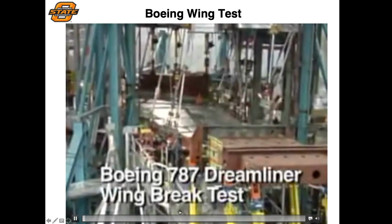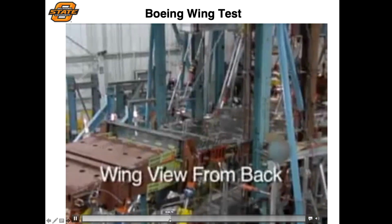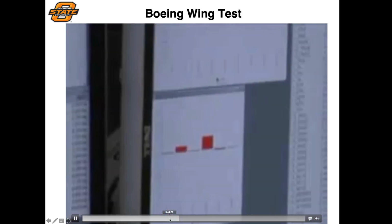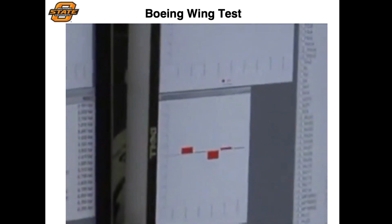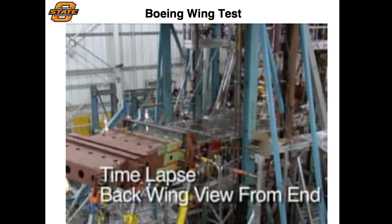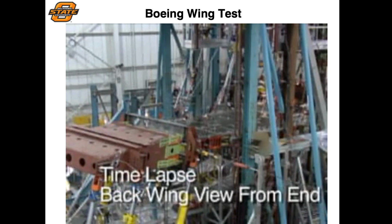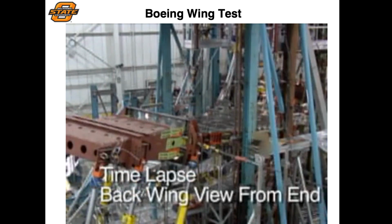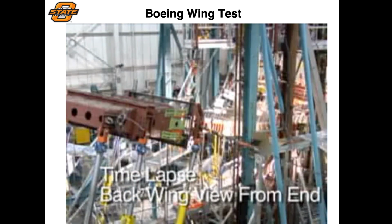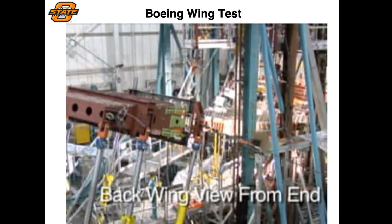So I'm not going to show this entire video here, but you can get an idea of the 787 wing break test as it's going through this process. Again, the jig that is built around this is used to push the wings through this simulated loading scenario, so that way you can measure the load and evaluate exactly what point it breaks at, that 150% or greater mark.